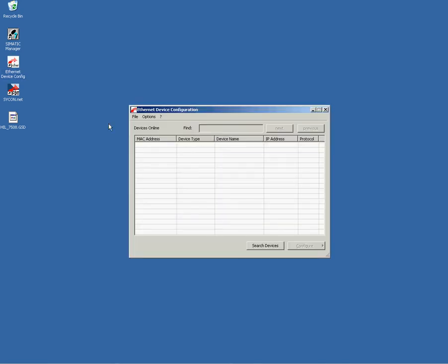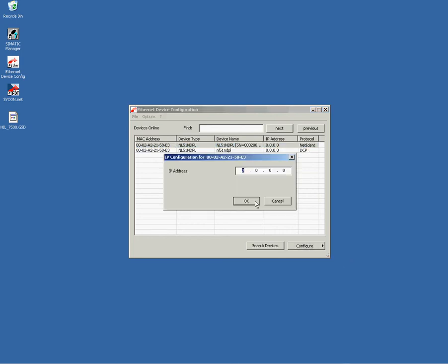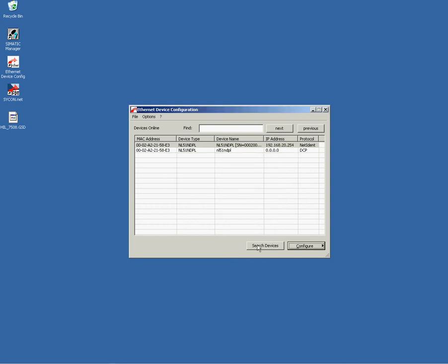The very first utility you have to use is the Ethernet device utility. This program scans for Hilscher devices via broadcast messages. So press the scan button and you see here the program has found my netLINK device connected to my local subnet. When you click into the row NetIdent protocol with the right mouse button and say configure, you can now set up the netLINK proxy's IP address.